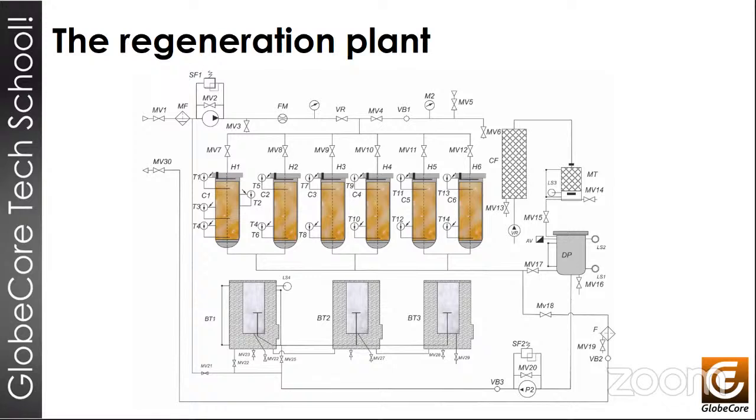Okay. So we drain the oil from the columns and we ignite the contaminants in the columns. And the process is like a cigar. There is a burning layer that moves down from top to bottom and burns out everything that the Fuller's Earth accumulated. And as soon as this high temperature process is over and the temperature in the columns decreases, we use the oil from the buffer tank. We supply it back into the columns, and then the regeneration process is resumed.